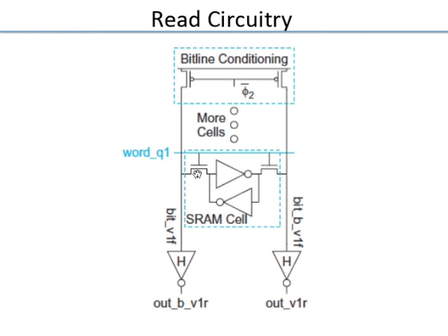Now, if there is a problem where maybe this was 0 but there was an error, a malfunctioning memory cell, that's not good. Because when both are high, you don't know which is the problem. Was it a 0 on the left side which was not disconnected, or a 0 on the right side which was disconnected? You can't make that out. So really there is no additional information from this pair of bit lines.